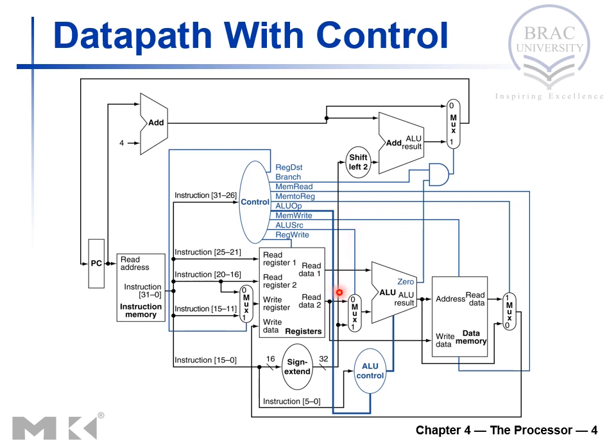For example, when we are performing an add operation, port 0 will be enabled, and when we are performing an add I operation, port 1 would be enabled. And then we have memory write. This signal will be enabled when we are performing a store operation. And then ALU opcode. This is a 2-bit signal, and it goes to the ALU control, and based on the 2-bit signal, it generates the 4-bit control for the ALU.